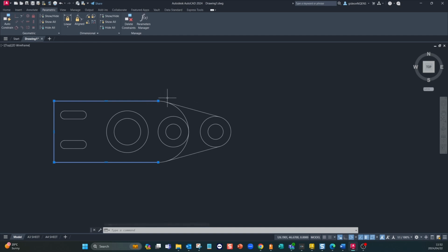We'll have to drag everything and move it and use the stretch command, or in some instances delete that specific part and redraw it, and then use our different snap points or override of snaps to place everything in the same orientation. Now, using constraints can really assist in this manner.